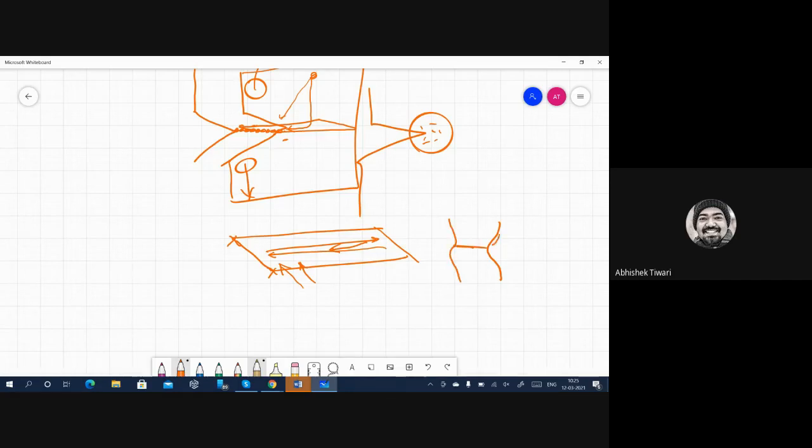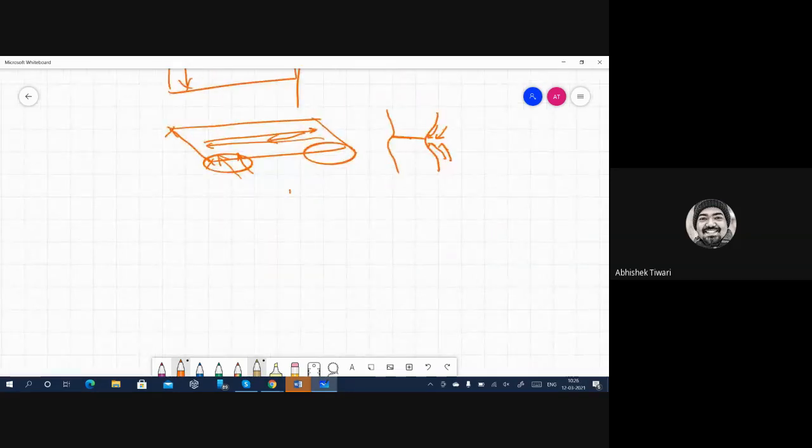So it will just go in. This is what we saw also in Charpy, where we saw the lateral strain. And this lateral strain was because at the tip you have demand and the material is being supplied. And because material is being supplied more from here, this thing goes in rather than this place. Same thing happens on the back side also. So you will see a three-dimensional material will have a sinking here and also on that side like this.